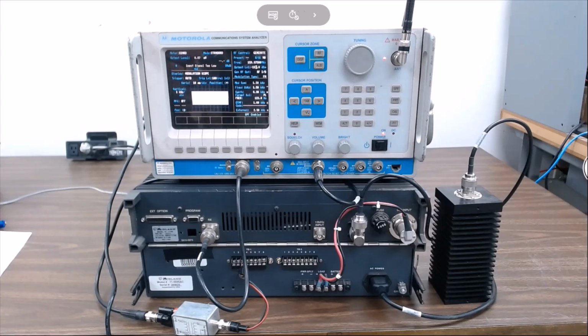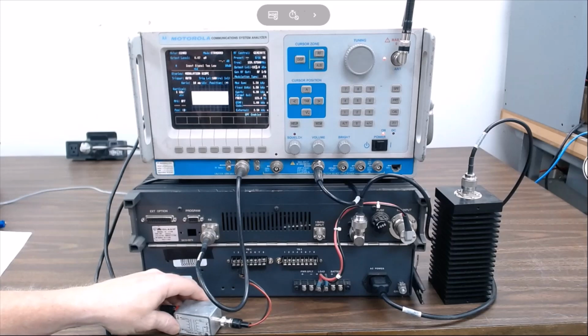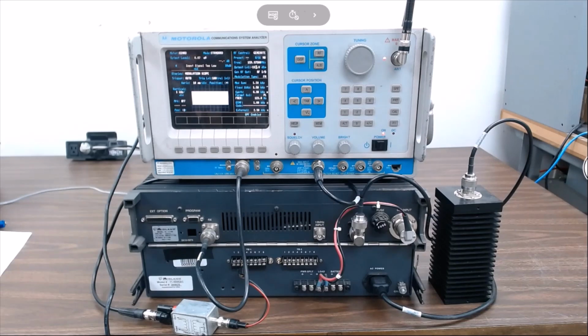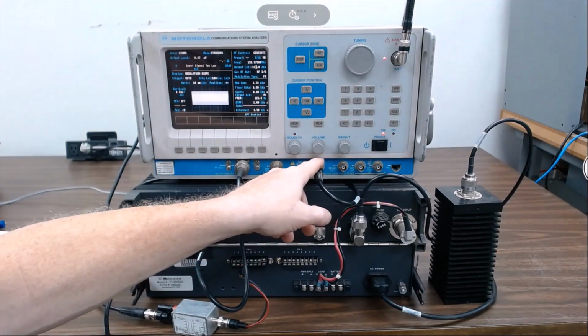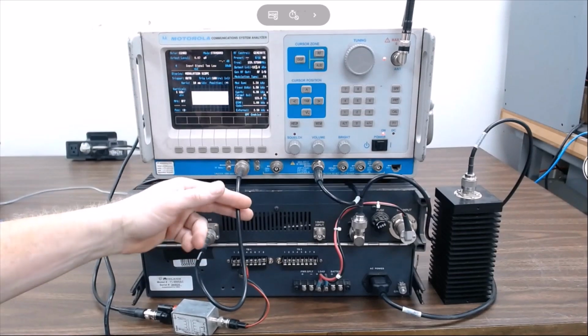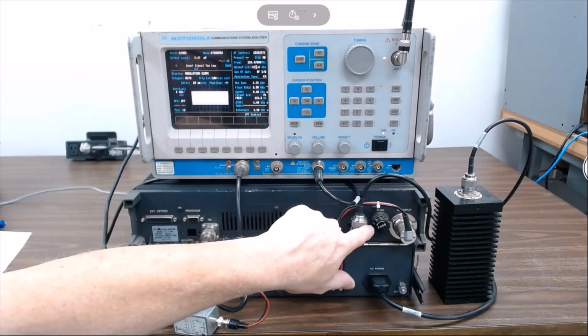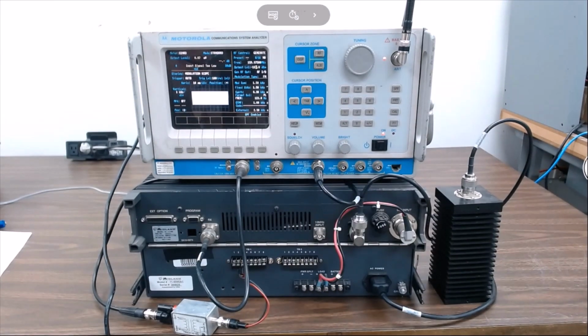We're going to be testing the receiver now. So I put the radio in monitor mode, and we're not going to be generating a PL tone, so we don't have to burn up our transmitter while we're doing these tests. I've added a one-to-one isolation transformer coming off my receive audio, and this is plugged into my sinad meter here. Still generator to receive, TR to receive, and my transmitter's on a dummy load as always.